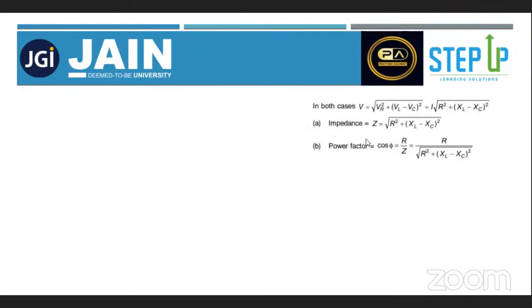Okay. In both the cases, to find the voltage, the formula is V equals root of VR square plus VL minus VC whole square, where VL is the voltage in the inductor and VC is the voltage in the capacitor. So we can write this as this formula also, where root of R square plus XL minus XC whole square is known as impedance. Okay. Power factor is equal to cos phi is equal to R upon Z, where Z is impedance. I will take this formula and put it here.